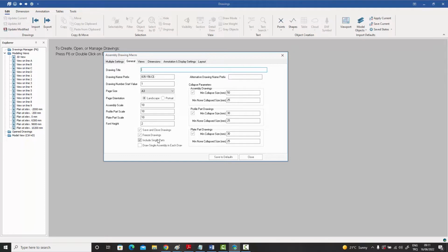So let's say you have an A0 size paper in which you're creating the drawings of your purlins. Now, purlins are pretty simple elements, and you can have maybe 25-30 different purlin assemblies in the same A0 drawing. So that's what we call a multi drawing, in which you have multiple assemblies in the same drawing.